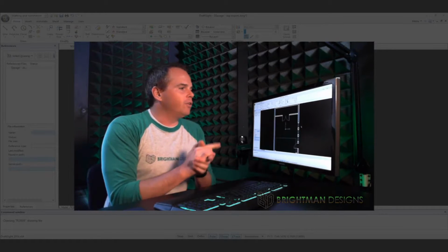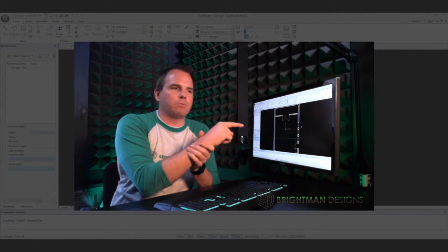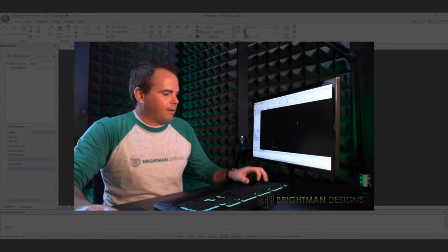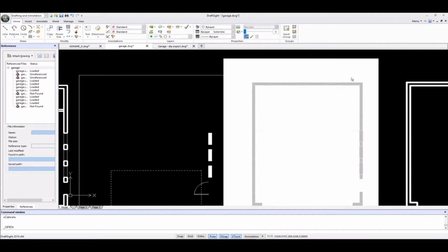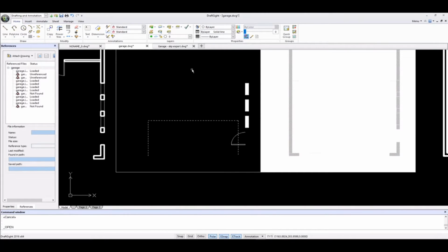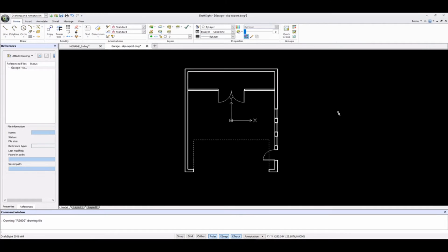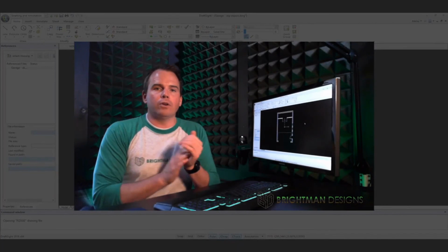So I would definitely opt for this method for exporting. The other export comes out with just too much junk. You don't want all these image renders and all that stuff to come out. So moving forward, I would just stick with this nice, clean, simple vector DWG export from SketchUp. All right, so that's a few tips on exporting for your consultants.